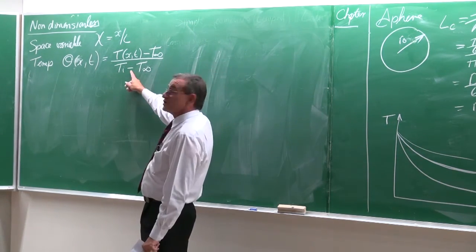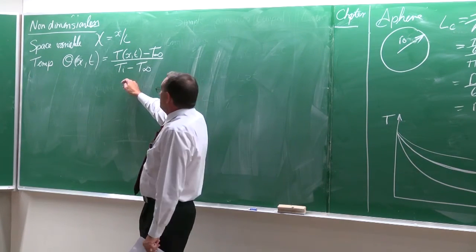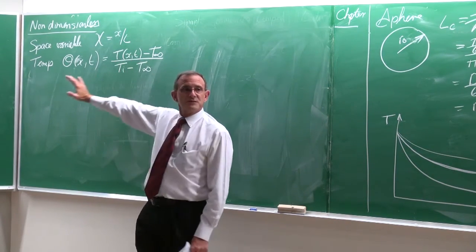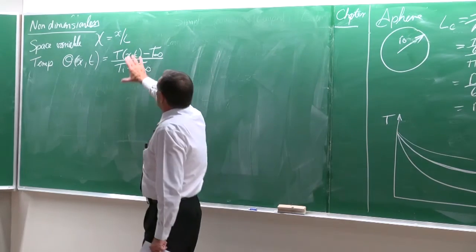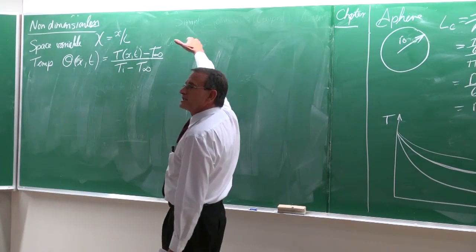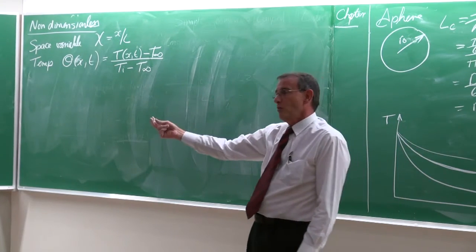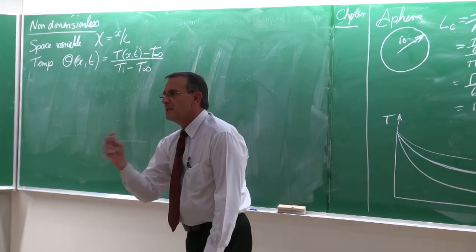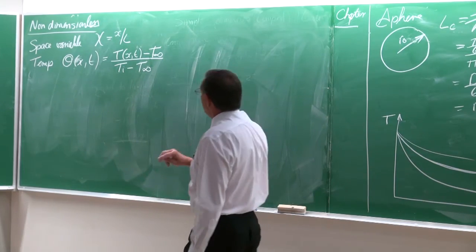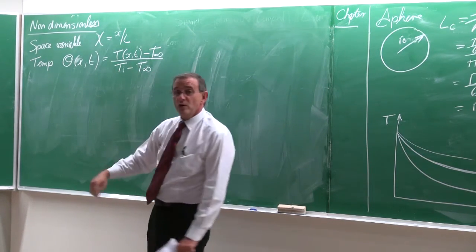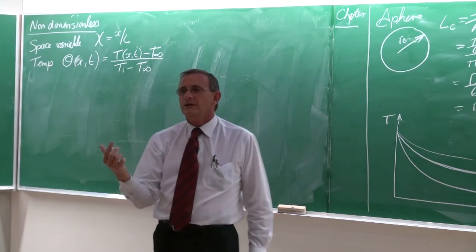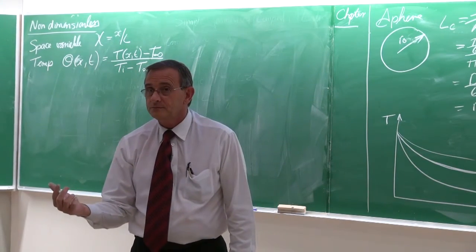If you compare this term to the temperature term that we had with the lumped system approach, which is equal to e to the minus bt, that has been written in the format of a non-dimensionalized temperature. Again, this will always vary between 0 and 1. It cannot have another value.